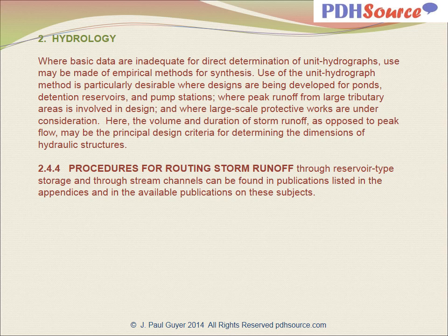Where basic data are inadequate for direct determination of unit hydrographs, use may be made of empirical methods for synthesis. Use of the unit hydrograph method is particularly desirable where designs are being developed for ponds, detention reservoirs, and pump stations, where peak runoff from large tributary areas is involved in design, and where large-scale protective works are under consideration.